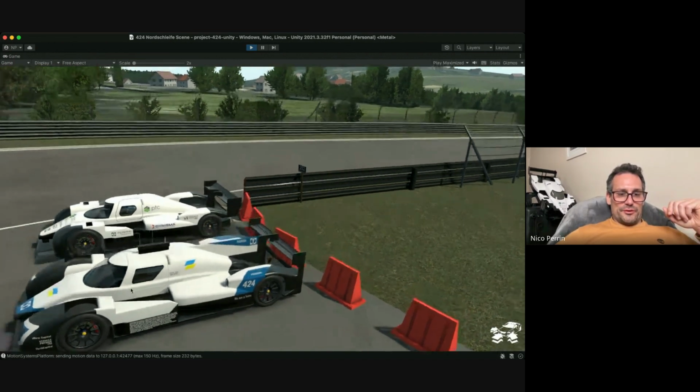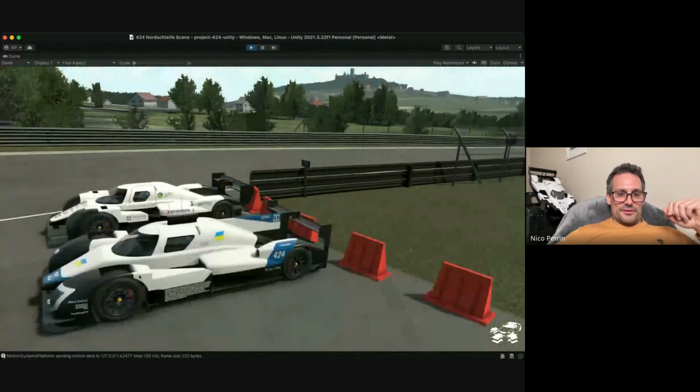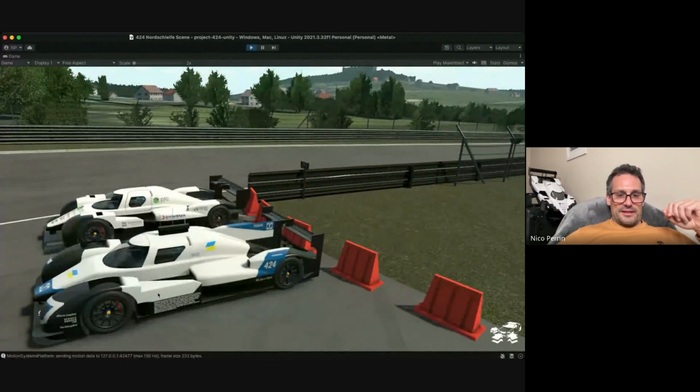And the same goes for the tail of the wheel arch. So the tail here, when you reduce the tail, you're basically allowing the floor to have more surface that is seen by the air and pressure applying on. But that will come with drag as well.